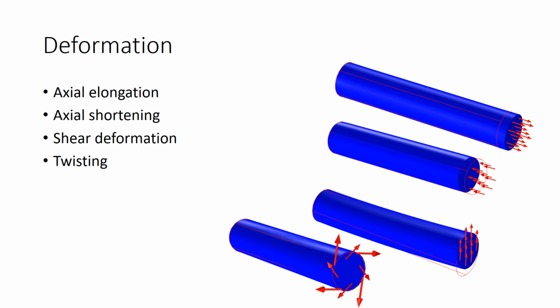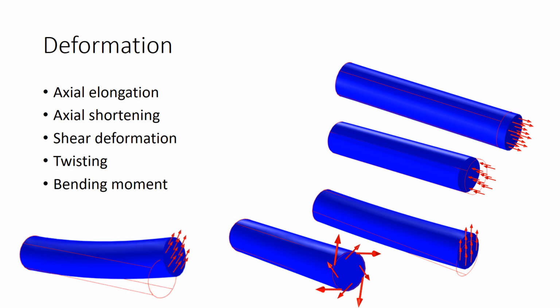The difference is, shear force will lead to in-plane deformation and twisting will lead to out-of-plane deformation. Bending moment bends the beam, and it will elongate one surface. After applying forces, all we need to check is whether the system is in equilibrium or not.